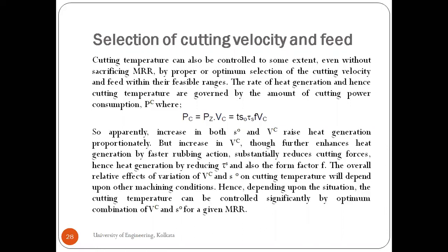However, some of the factors can be such that if you increase the cutting velocity, the cutting forces are reduced, definitely, as we have discussed previously as well. In that case, if the forces are reduced, power consumption will be reduced. So power consumption again is directly proportional to the cutting temperature. So there are many factors that come into the picture.